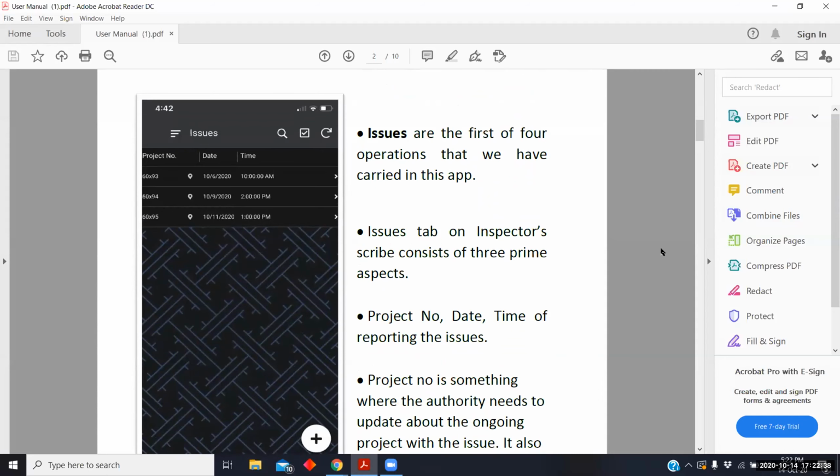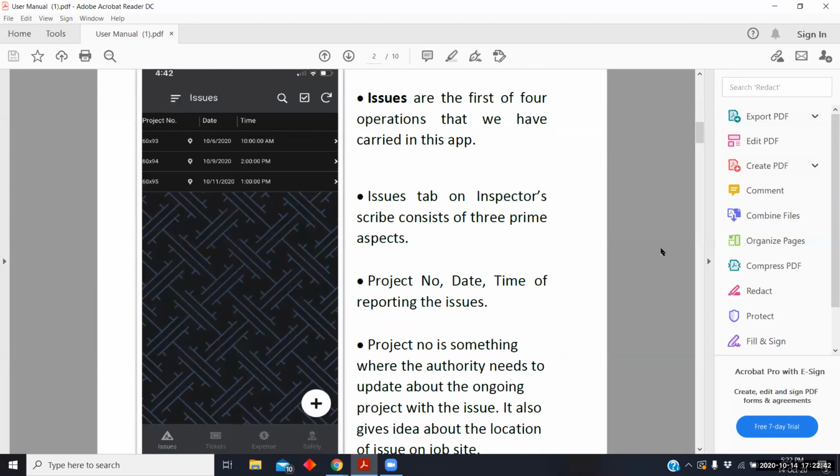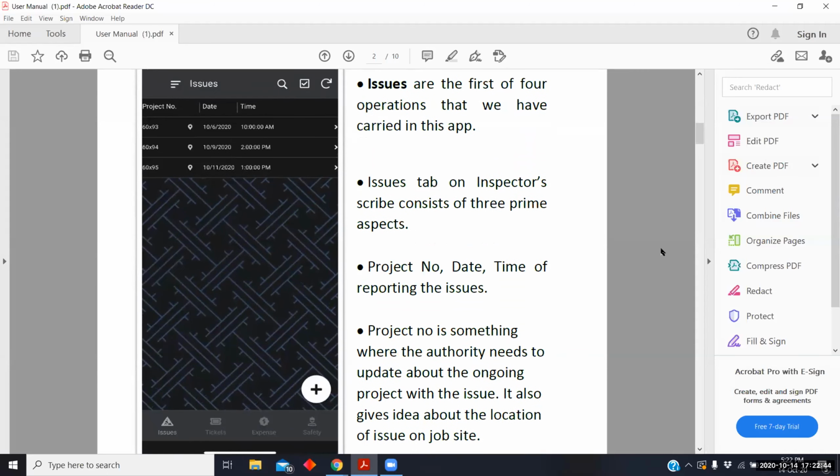As we noticed, there were a lot of issues caused on the job site. Sometimes there used to be an issue related to form work clearance, or an issue where the reinforced bars which we used to get on site weren't epoxy coated, and that's a major issue in terms of quality management and quality assurance.